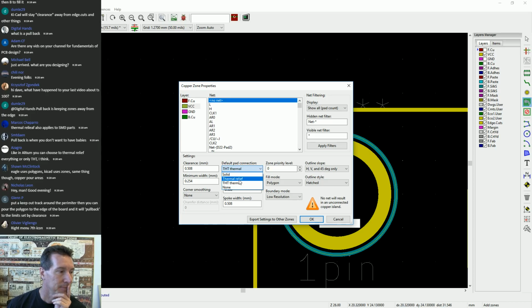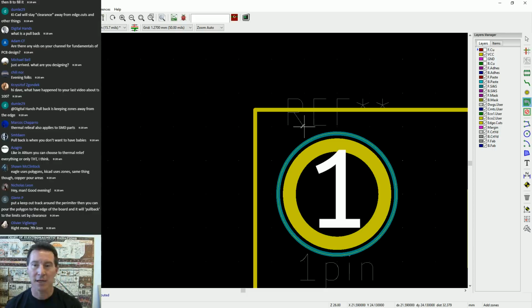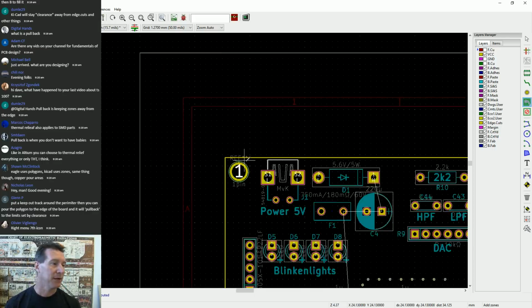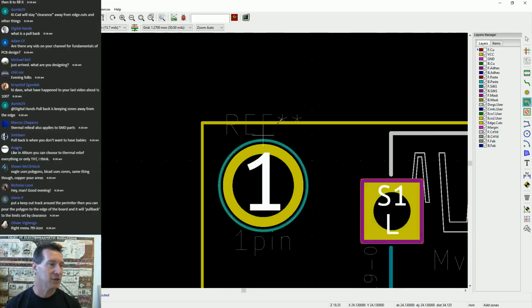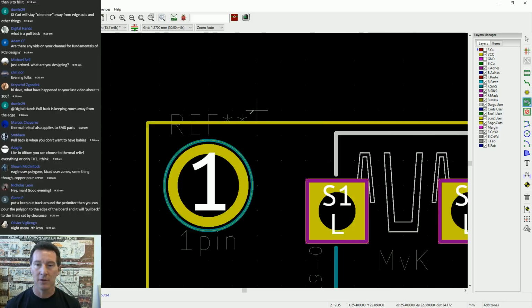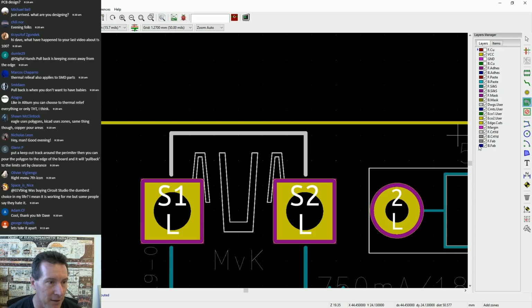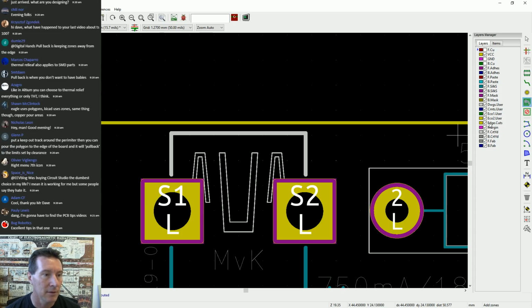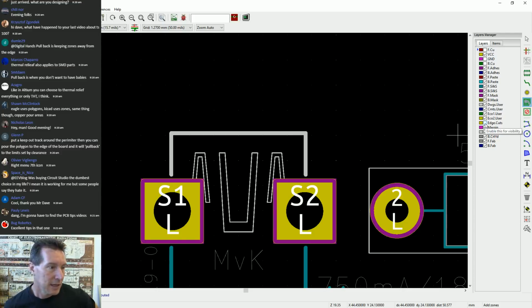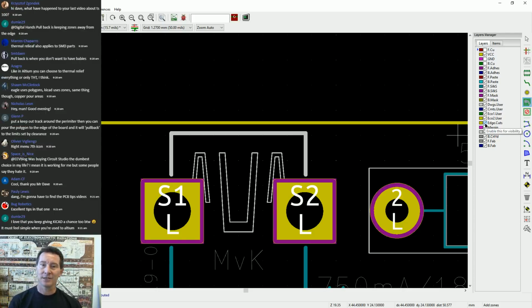Right, so, anyway, let's go out of here for a second. When you've got a PCB, you've got the edge of your board here. The edge is defined on this particular layer. I don't know which layer they use in KiCAD. Fabrication layer, is it? No, it's not the fab layer. Mask, pad, adhesive. Edge cuts, there we go. They've got an edge cuts layer, right?